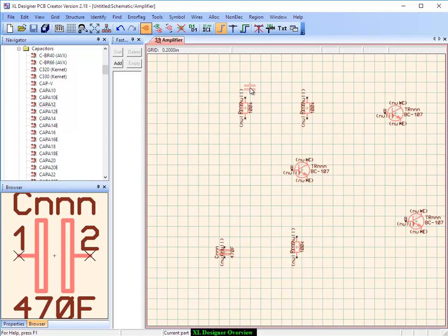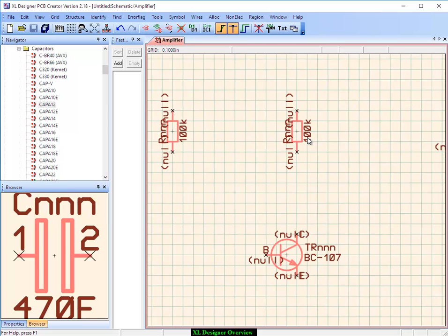And then we need to just start adding some wires. So we either use the shortcut icon for add wires, or under wires insert connection. And then we zoom in again if you want to, start the wire on a terminal and then release it on another terminal. You'll see the little crosses disappear to show that the connection has been made correctly.